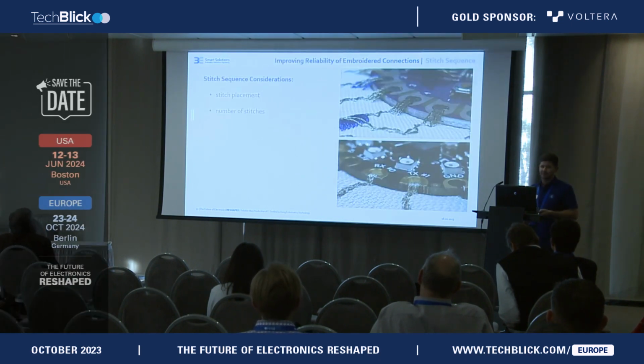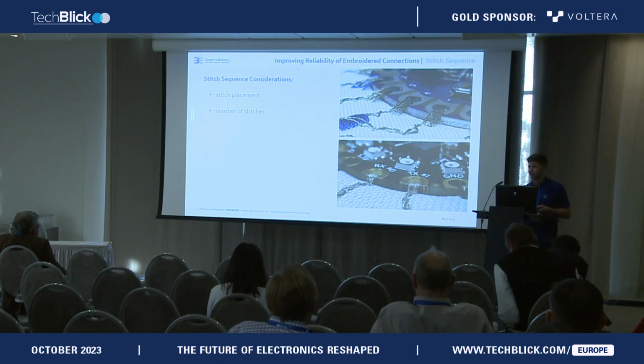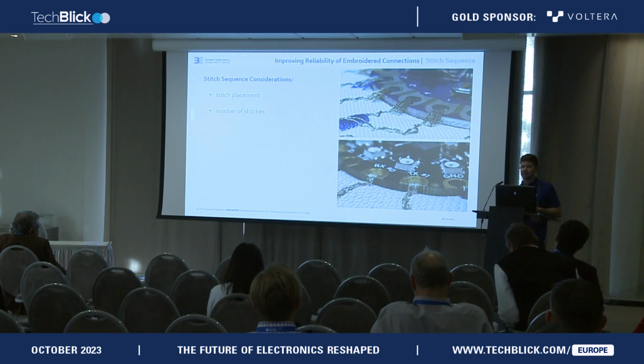So I'll talk about how we address these challenges one by one. Talking about the reliability of the embroidered connections, here you can see on the pictures some PCB boards that we started with. They're off the shelf, like the well-known LilyPad. First we tried to optimize the stitch parameters, so stitch placement or number of stitches, and we were able to improve the reliability of the connections to a certain extent, but we wanted to go a step further.